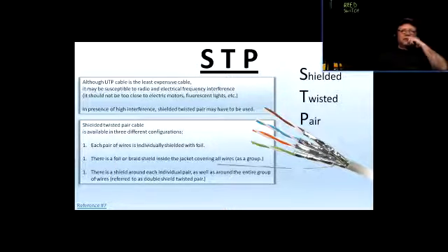But if you are installing a network or control wiring that employs Ethernet communication in something like a production plant, where you have robotics going on, machinery, PLCs, all that stuff, the control systems, then I would say almost 100%, if not 100%, you're going to be required to install shielded twisted pair, because those wires are running along the machines that have motors or whatnot.